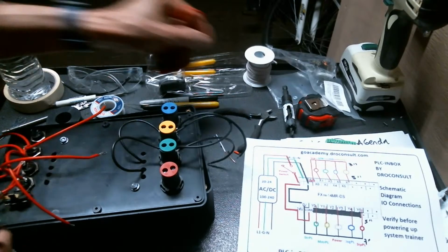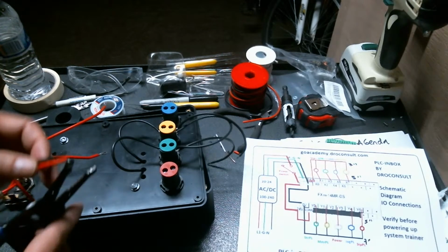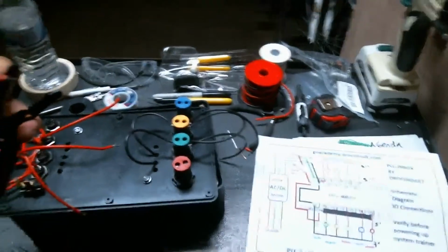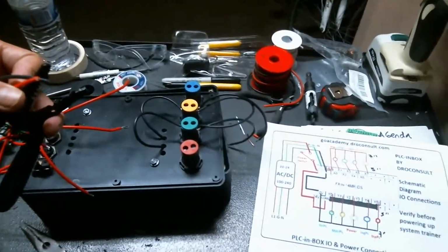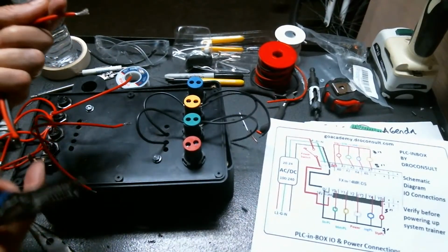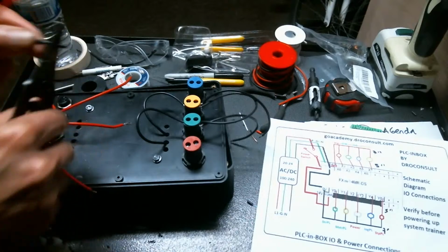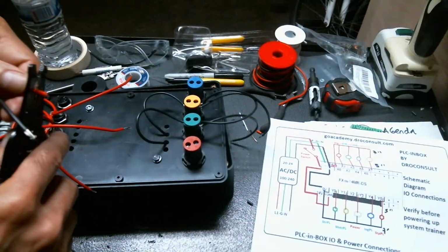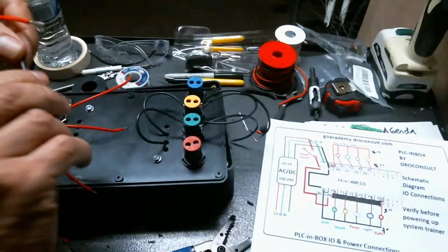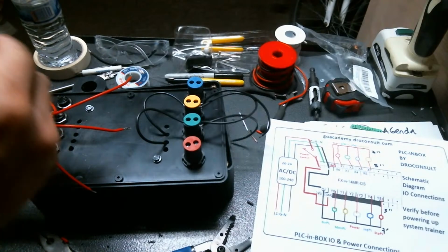Enough room for what we need to do here. And then you want to strip those wires, and when you strip the insulation out, you also want to tin these wires. So strip and tin, because usually with stranded wire, if you don't tin the ends, the wire tends to be all spread out, and so it's hard to make contact. So tinning these wires is always a good practice.